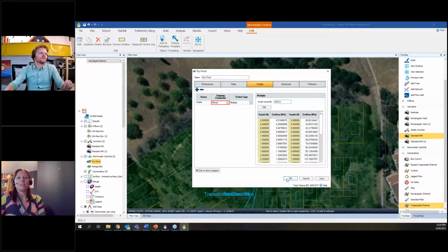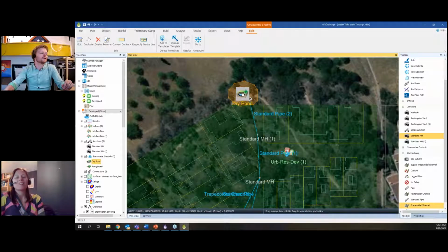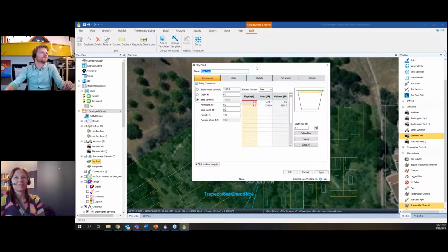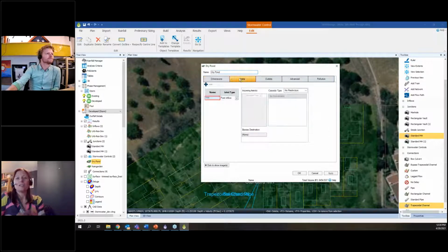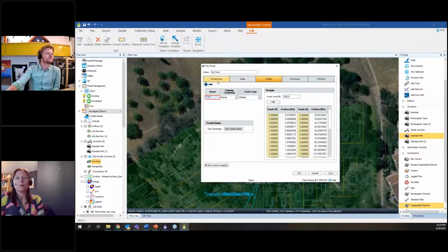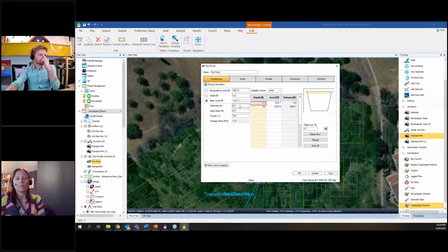Before you leave the pond form... There was a question about groundwater being incorporated into the design of the pond. So I thought it was maybe just worth pointing out the initial depth option on that screen there where you are now. Essentially any sizing calculator is going to work above that initial depth option.